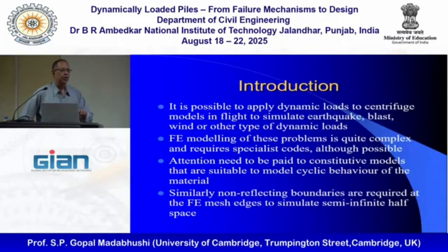So you can't look at soil behavior just in stress space. Although we traditionally draw Mohr circles totally in stress space, what is important is what is happening on the third axis, where the void ratio or specific volume is also changing. So your constitutive model needs to be able to handle that as well.